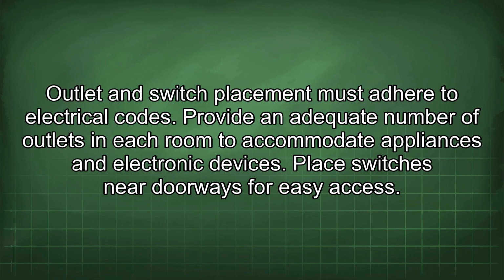Outlet and switch placement must adhere to electrical codes. Provide an adequate number of outlets in each room to accommodate appliances and electronic devices. Place switches near doorways for easy access.